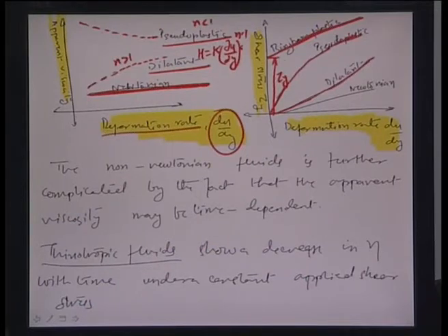But as you plot the shear stress, tau x y really would be equal to this k times |du by dy| to the power of n minus 1 times du by dy, which means that there is an increase in shear stress tau x y because of an increase in du by dy in both the cases.